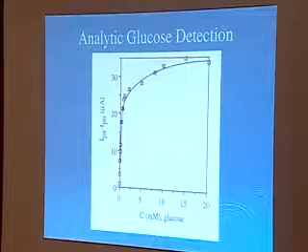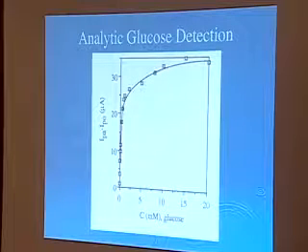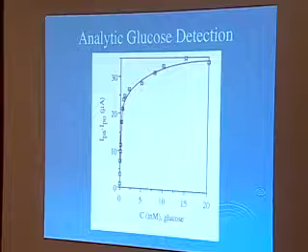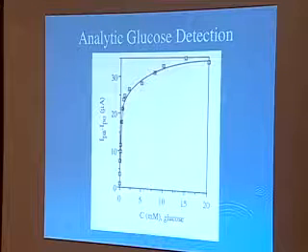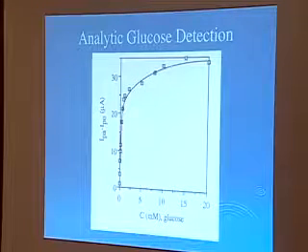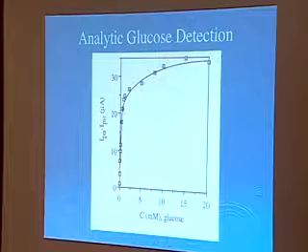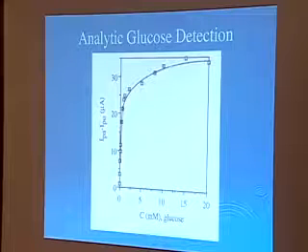We have a low glucose concentration region and a higher region that we can both linearize if we want. So we have a nice sensor system, as long as you tell me which region you want to look in. It turns out this one down here, if your glucose levels are that low, then you're not breathing, or breathing too much or something. You need more glucose in you.